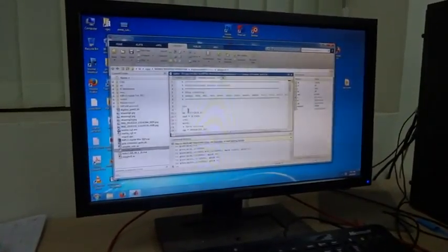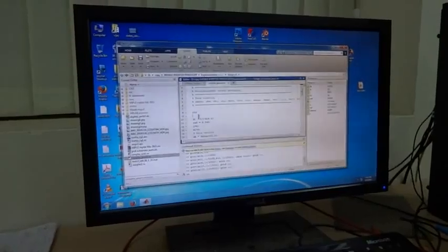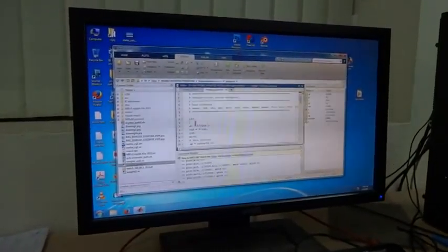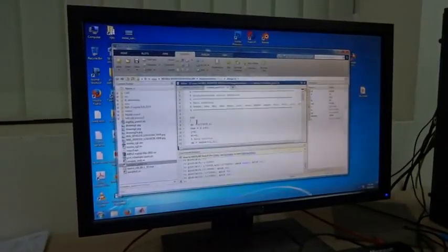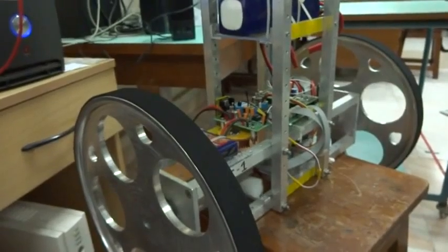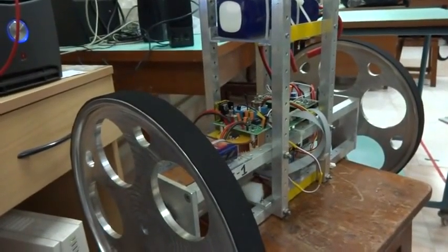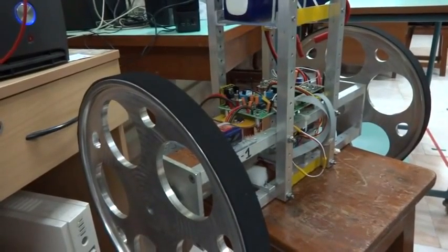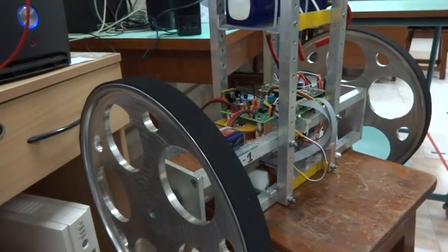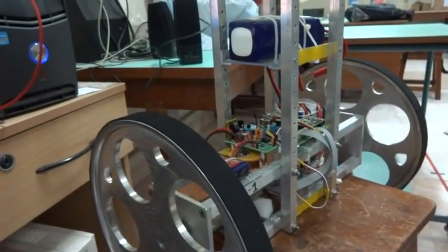Now we will show how the data can be directly received in Matlab, and the example problem will be a position stabilization code running on the MIP robot, which will transmit all 7 states and the 2 applied motor voltages and the 2 battery voltages. So in total, 11 states are transmitted through the ZigBee module.